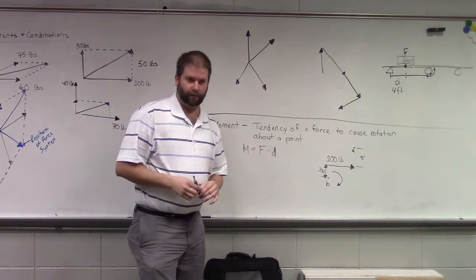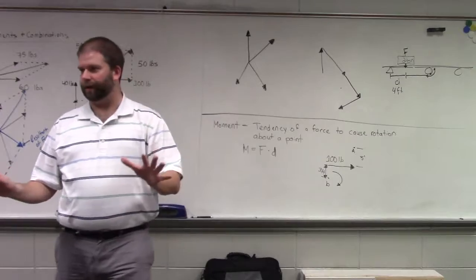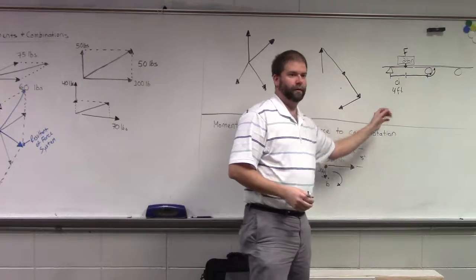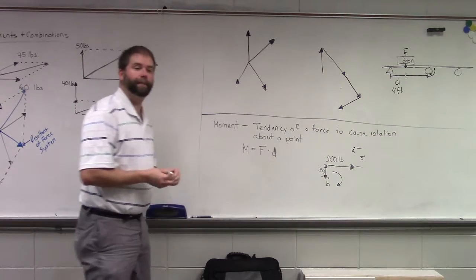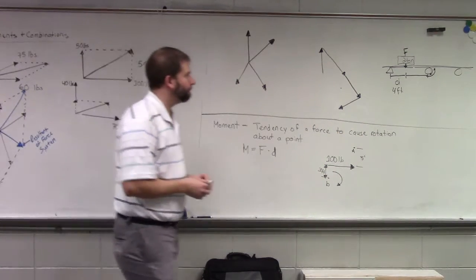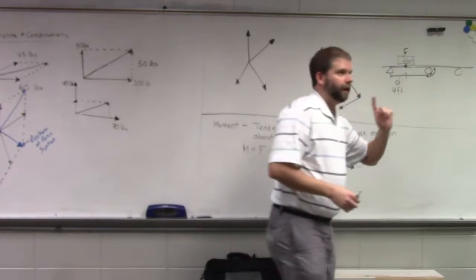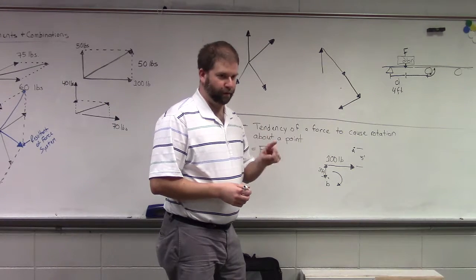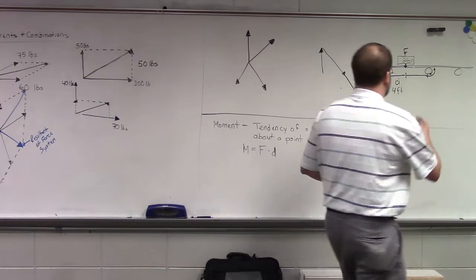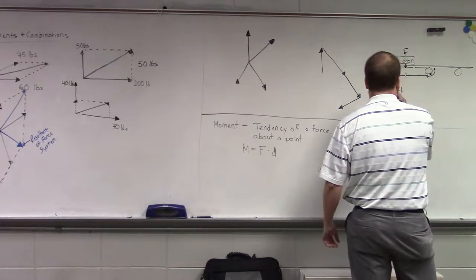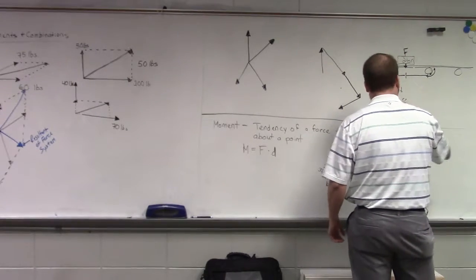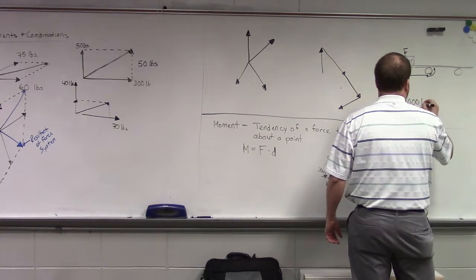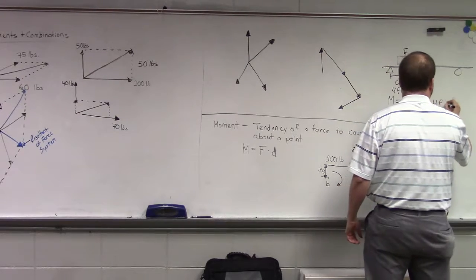But it's okay. I know this isn't something that we measure out in the field, right? How do you measure a pound foot? It's not pounds per foot, it's pound foot, okay? So your equation is going to be moment equals 4,000 pounds times 4 foot, which is 16,000 pound foot.